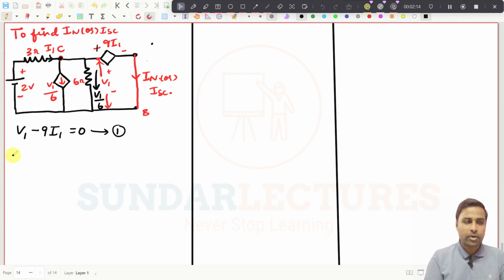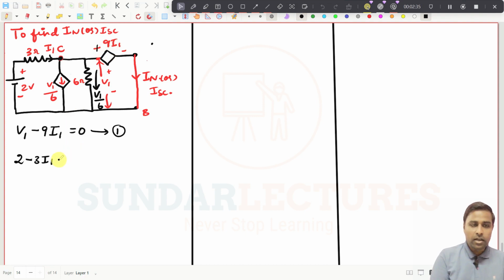So start from this point, it will be plus 2, going from minus to plus. In this way, the current and the direction I am going are the same, so I have to put minus 3 into I1, and then I will go in this direction. Here in a voltage source, I am going from plus to minus, so it will be minus 9 into I1. That's all. I have completed the loop, which is equal to 0.